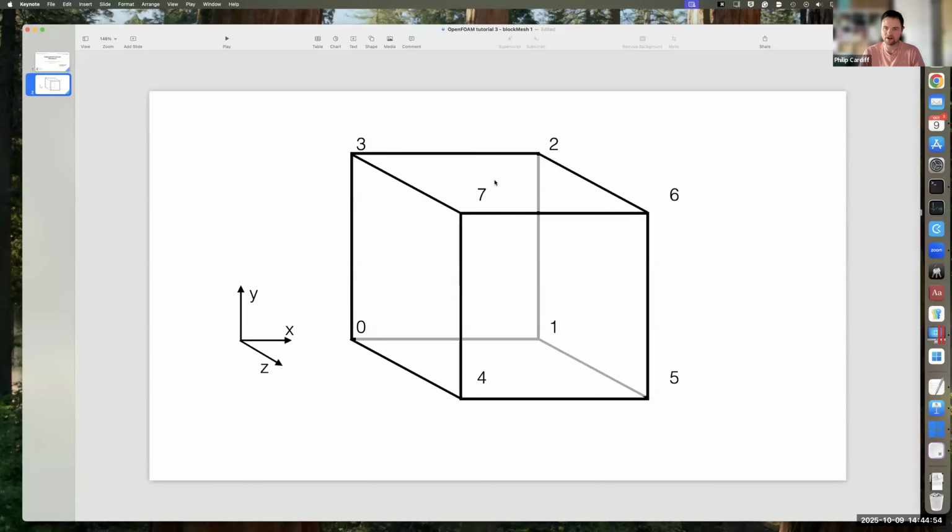So there is a convention for the direction that's defined. It's the right-hand rule. So you can start at any one of these 4 vertices. And then if you use your right hand with your fingers curled, with your thumb pointing out of the geometry, so an outward facing normal, then you just go in the direction of your curved fingers. So if I picked 2, I would go 2, 3, 7, 6, or 3, 7, 6, 2, or 6, 2, 3, 7. As long as you're going in that same direction with your thumb pointing outwards, all of those are valid.